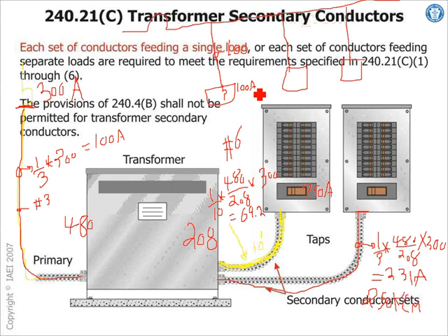Okay, so we got that one. Okay, secondary conductor is not over 25 feet. Now, if this secondary conductor is not over 25 feet long, they go 1/3. Now, the last tap, guys, is that yellow one here. They allow you to make this one 25 feet too. If this conductor is 25 feet, then it becomes 1/3. Only that conductor, the same thing, 1/3 of 480